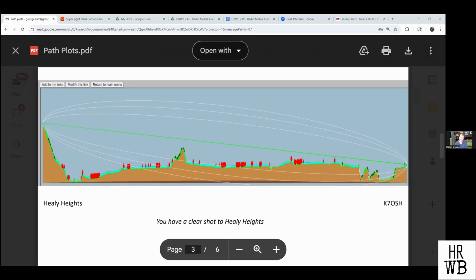In UHF, you can go below because there is less noise, but you still have noise. So let's say that the typical FM receiver is going to be 0.12 microvolts for 12 dB of quieting. Would you just go with that? I will never go with that with a mobile.